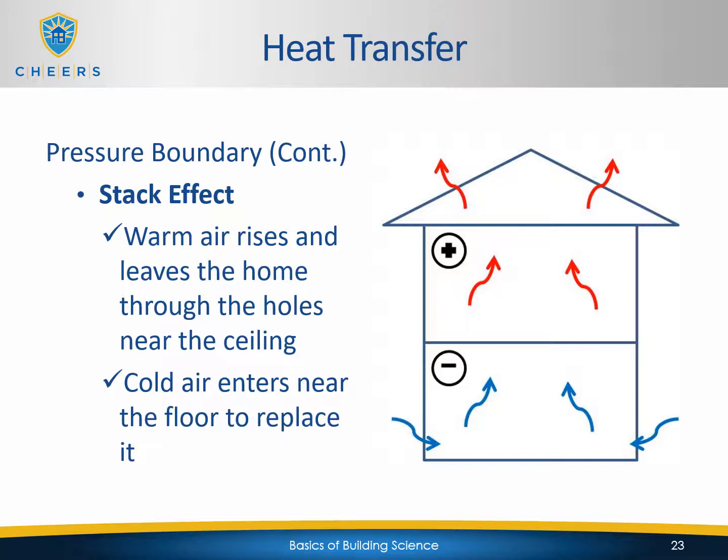Now, given the fact that that's a constant airflow, it's uncontrolled constant airflow, that's going to create a convection loop within the actual house. So as air is being heated and rising to the top, it's going to be sucking cold air from the bottom. So it becomes almost a vacuum effect within the home itself that perpetually keeps the convection loop going. So hot air pushes up, sucks cold air from the bottom, and it just keeps going.